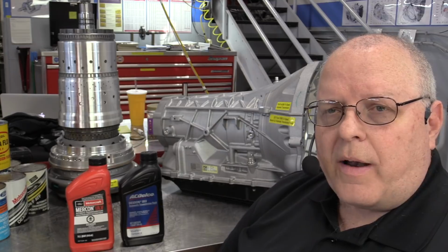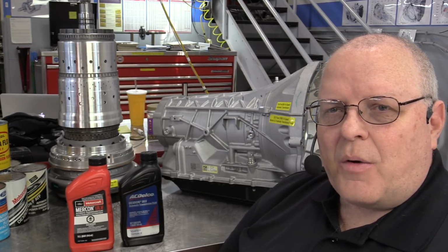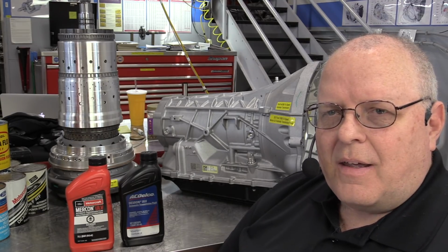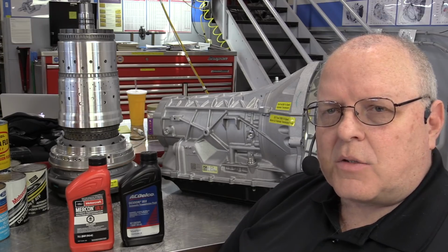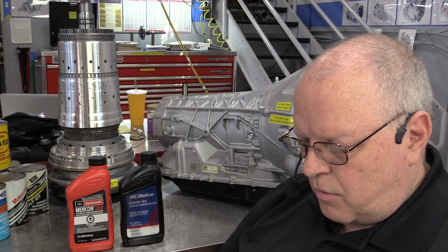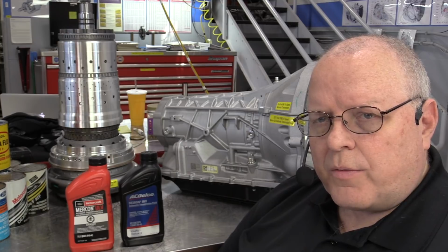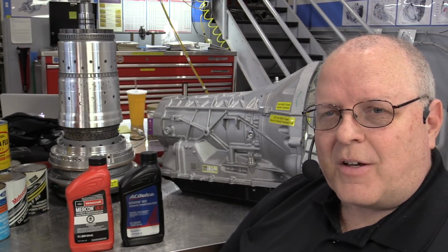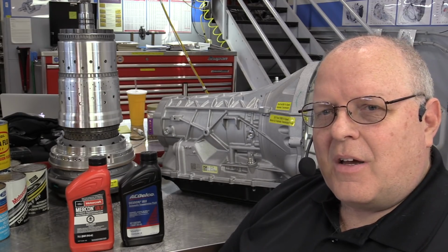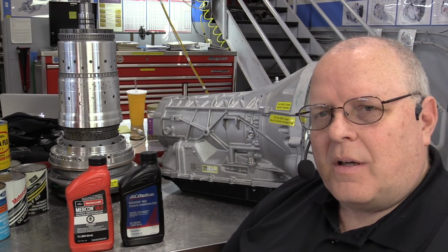I told you that we would find out when transmission fluid turned red. As we saw, there were aftermarket additives, dyes, to turn that fluid red in the 50s and 60s, and it wasn't until Dexron II that it was an actual requirement that it be red for General Motors transmission fluids. We looked at the service intervals for fluids. We saw that we started around 5,000 miles, went to 10, 12, 24,000, 50,000, 100,000, and the supposed lifetime fluid.